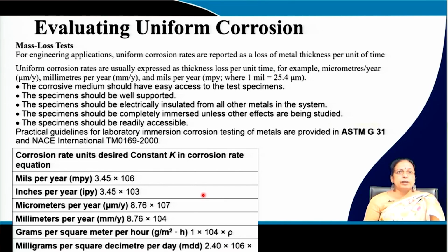So, there you can use the typical potentials with the help of a potentiostat, you can apply electrochemical testing, or otherwise you can also apply simple mass loss testing or standard coupon testing, where you keep the component in the given environment for a specified period of time and you try to record the mass loss or mass gain per unit area, and finally you do the testing for an average period of 1 month or 2 months or maybe 5 months.